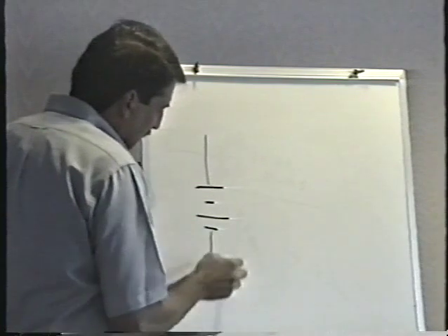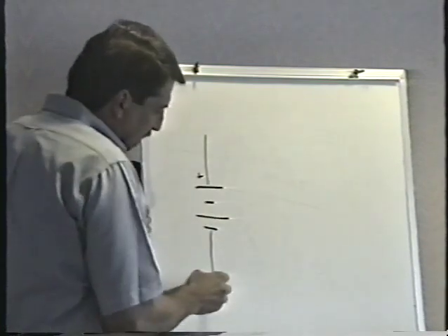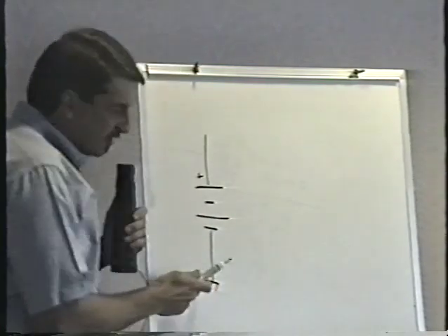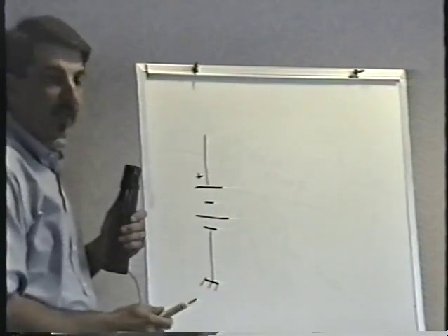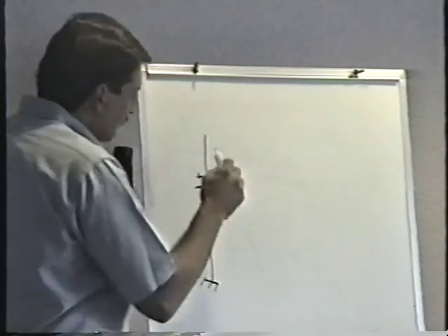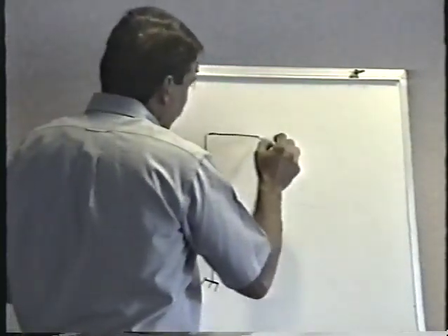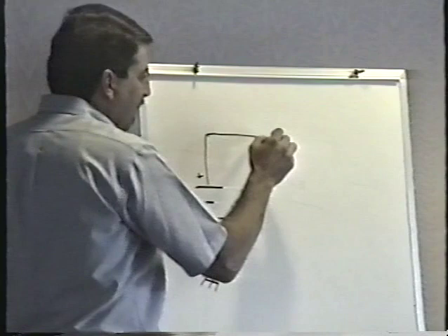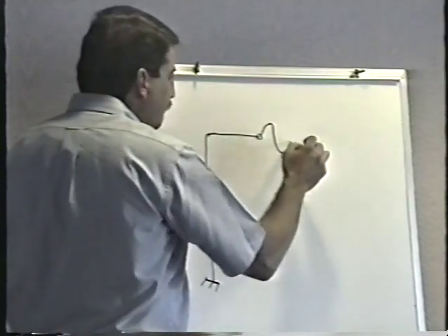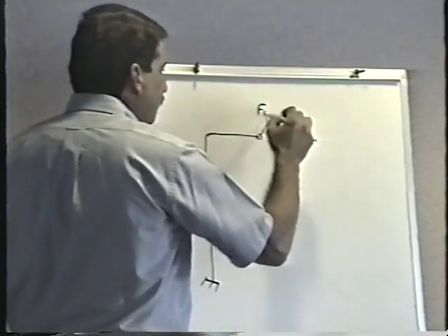So here's our car battery and negative ground. And remember, that's the chassis ground symbol that we looked at yesterday. And it's a 12-volt car battery. And the current would leave the battery, and presumably it would go through a fuse first. And this is the schematic symbol for a fuse.